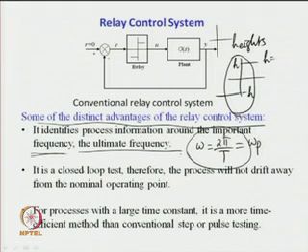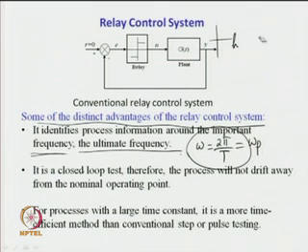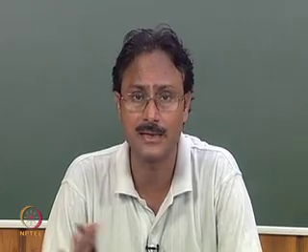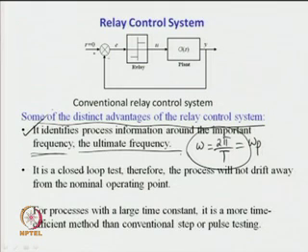One can try from 0.01 to some higher values like 1 and so on. Unlike the earlier cases where one has to be very careful when one increases the proportional gains, here the relay heights can be increased gradually without fearing for anything, because the output will definitely remain sustained oscillatory in spite of any setting of relay heights. So, this is what we get from the first point.